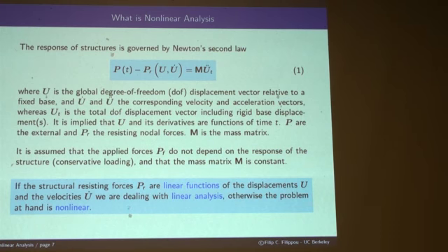Because the fluid pressure is always normal to the surface under certain frictionless conditions. And so if the surface deforms, like when the wind blows, then you have to account for P as a function of U as well. That alone would give you a nonlinear analysis situation, right? I hope that this is clear.